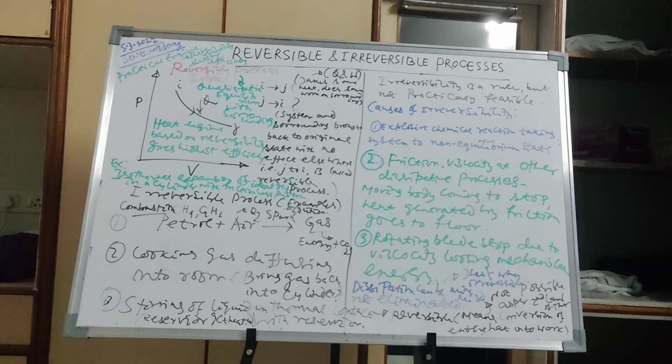Now, in your curriculum, the Carnot cycle is there. So how to find the efficiency of a Carnot engine? The Carnot engine is an ideal engine. It actually does not exist in reality. It's not a practical engine. It's an ideal engine. It has two isothermal processes and two adiabatic processes. All four of these processes are reversible processes.